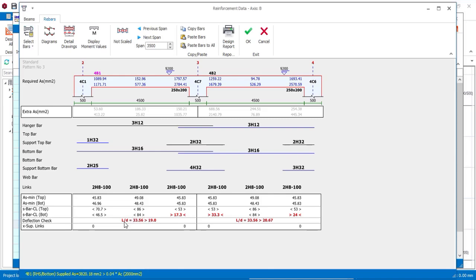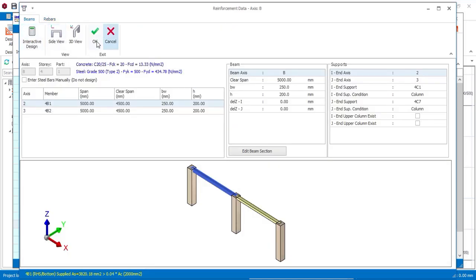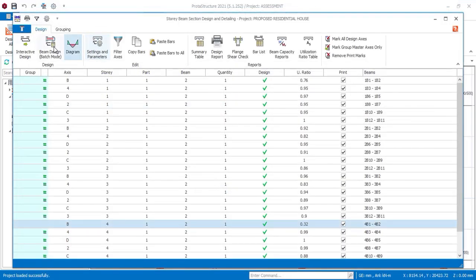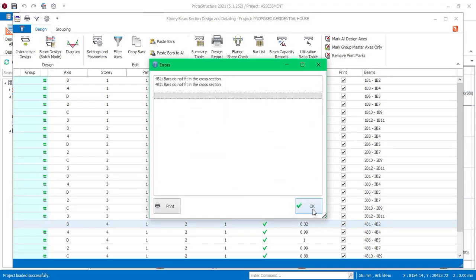In order to reduce the deflection, we have to change the height of the beam. Come to the beams and then change the height from here, let's say to 400 again, then to 400 again. We click in the upper one such that this one also changes to 400 and press OK. Already it's okay, so double click on it and press OK.